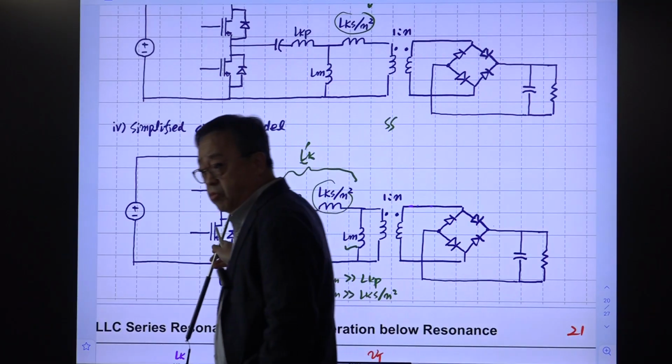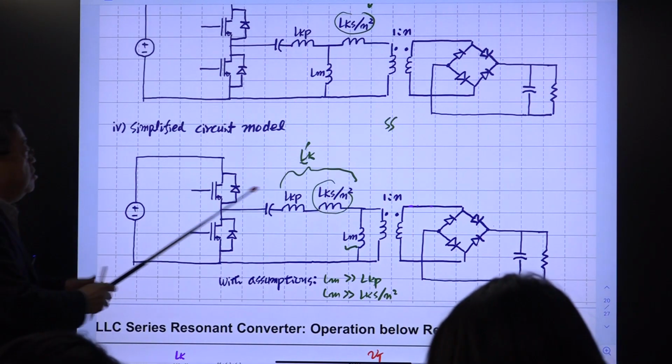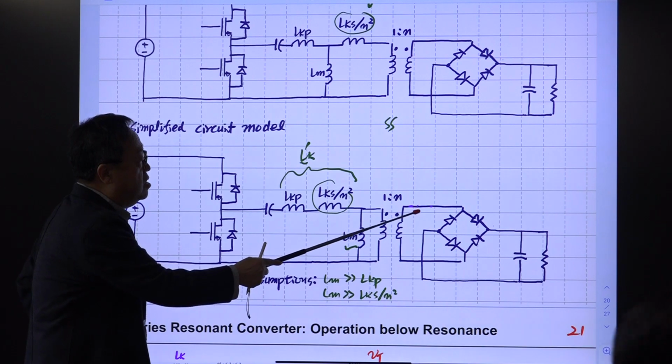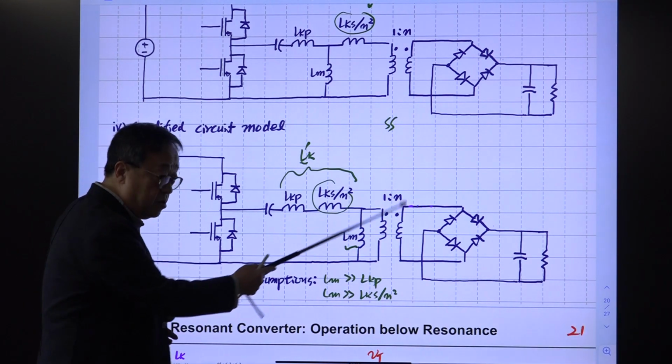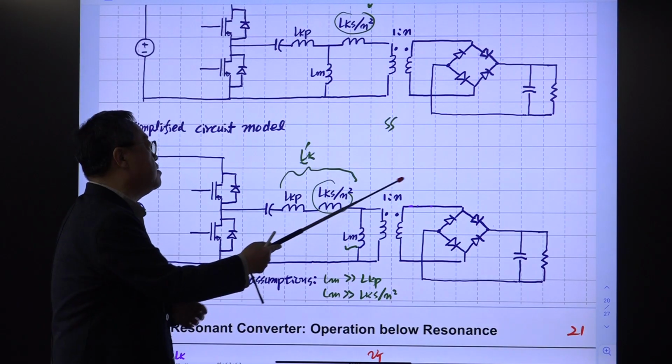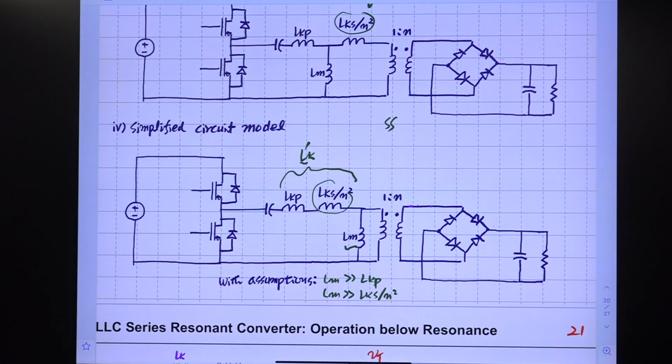But I thought about this a long time ago when I was studying this for the first time. The thing is, actually there is an inductance here. Originally, the leakage inductance of the secondary winding was here, but we moved it artificially with some approximations. So we should consider there is an inductor path.